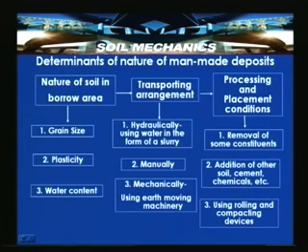The transporting arrangement for constructing man-made fills is also done hydraulically, using water in the form of a slurry. This fill construction is called hydraulic fill construction. It is adopted for reclaiming land in large areas, for example over hectares of area, to develop the land with a highly compacted soil base.